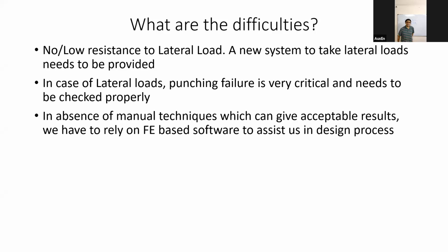This is how load transfer takes place in a typical slab beam column system. The slab first transfers its load to the beam, and then there is a frame action between my beam and column, portal action you can say.